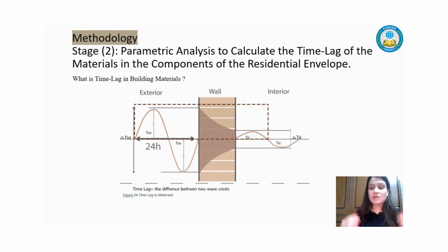What is time lag? Time lag is the amount of time that the residential envelope will resist the exterior temperature entering the interior, or vice versa, the interior temperature escaping to the outdoors, which means that the more the time lag, the better.